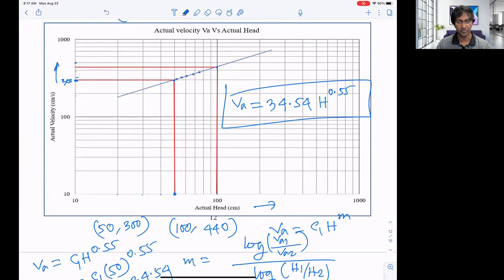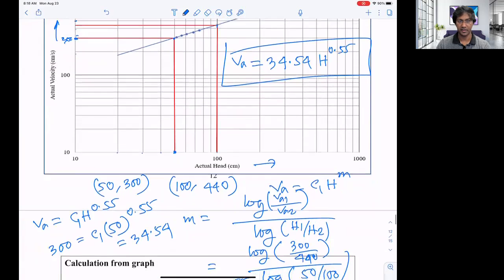So that is the orifice. It is pretty simple. If we have a small opening, right, then you can measure the actual head over this opening, and then you can use this equation to calculate the actual flow rate and actual velocity as well. This is a pretty simple equation, and it is very effective to measure the flow rate, or to control the head of a reservoir. So we can use an orifice meter. Next we'll see another device.